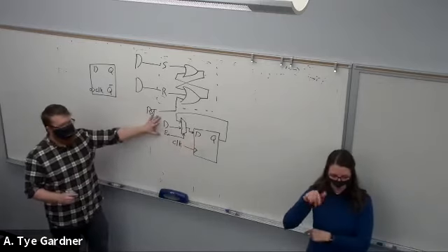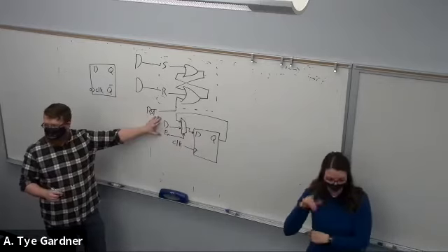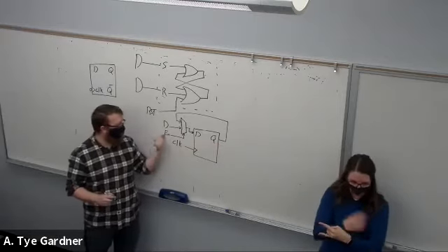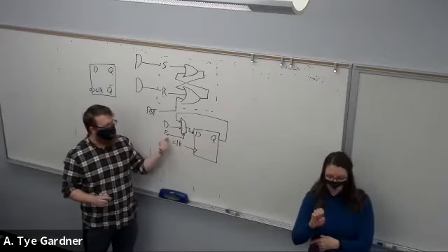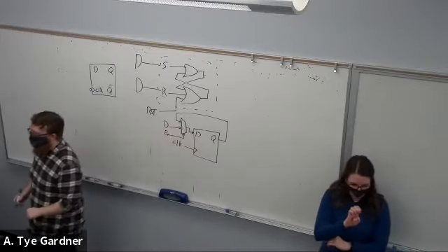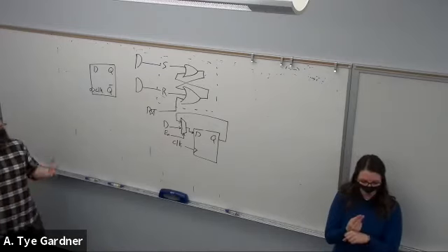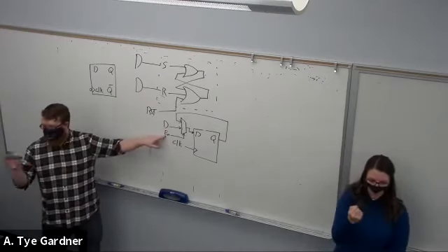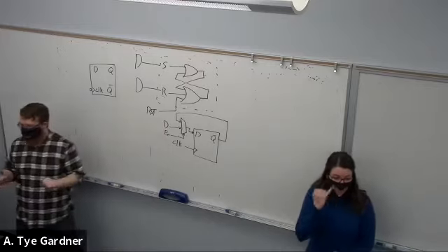So this way we avoid that gated clock problem. We use this feedback to say, if the clock happens and I don't have enable, then let's just take the old value and keep holding on. This keeps it fully synchronous. There's no gating issues. The enable isn't going to cause weird oscillations in our clock. Everything's happy.